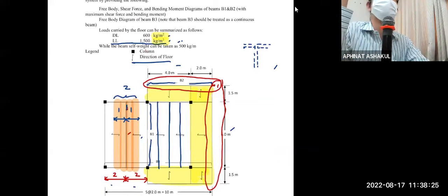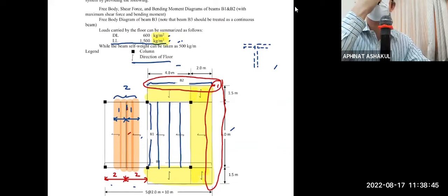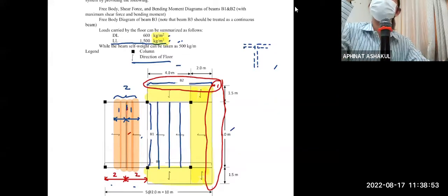So if you use, say, not a lot of beams, the floor will become large and thick and heavy, and your beam will therefore carry more weight and more moment. There will be a time when, wow, we cannot build a bigger beam than this due to some limitations. So this becomes a solution: add more beams so that the beams and the floors become smaller.